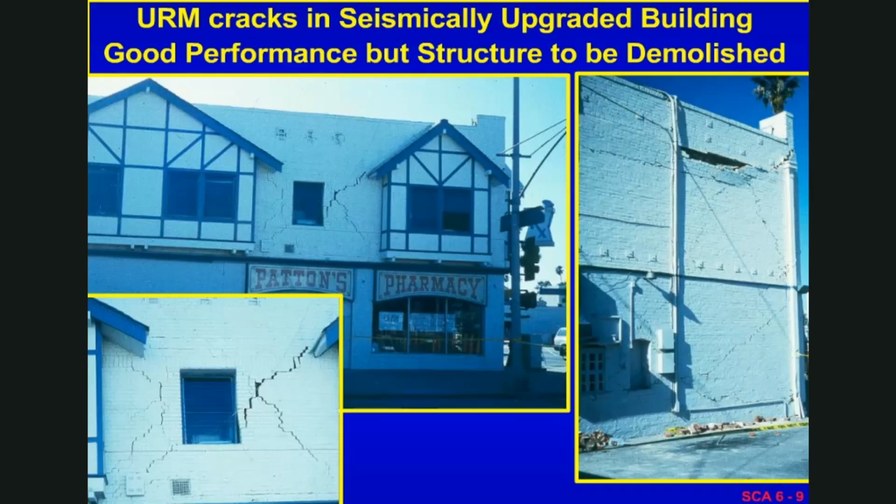But there are little things you can notice in the right-hand picture about how buildings operate. You'll see there's a fairly large crack that occurs near where the roof intersects the wall, and that's how the building was trying to resist the wall pushing against the roof. It was not quite strong enough to work its way without doing a large crack, but nonetheless it stood up, just to give you some idea of how these things work together.